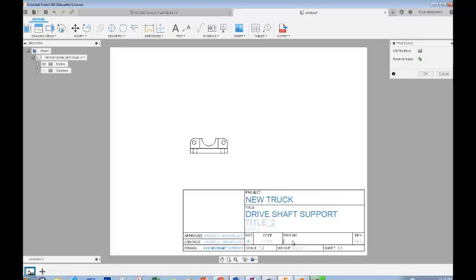Alright, we're going to just come up with a fake drawing number here, just 1, 2, 3, 4, 5. Okay. Let's say we modeled this part as a weight of 0.2. Put a 0 in front, 0.2 kilograms. Hit enter. And it's going to be a revision A. Okay, that looks good. Fusion automatically puts your name and date in if you're logged in as yourself. Okay, and then just say OK up here in this box, and it goes back to black, meaning it's off of the title block management.